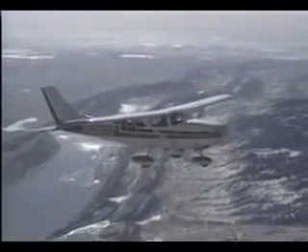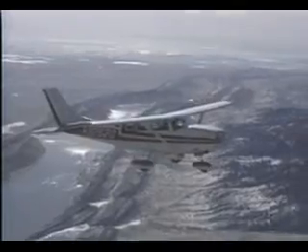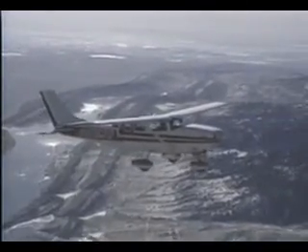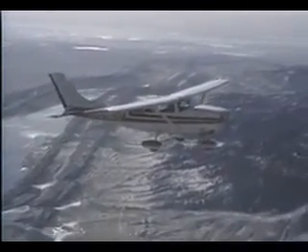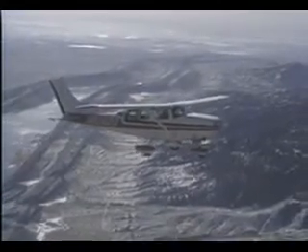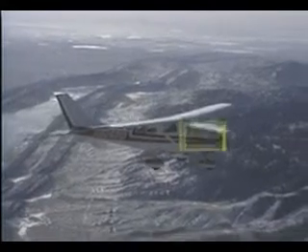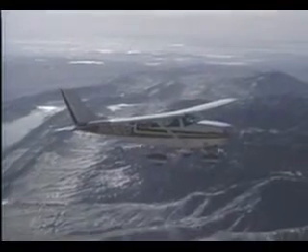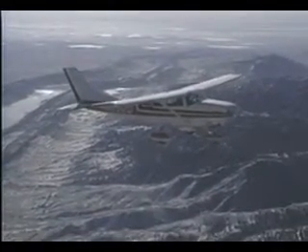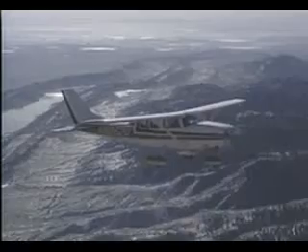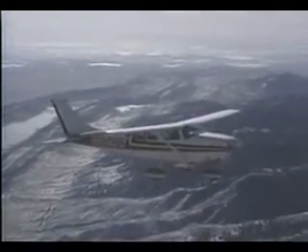Whether you fly airplanes with a carburetor or fuel injection, engine efficiency decreases as you gain altitude, and thus the density of the air entering the engine is reduced. To overcome this drawback, some engines incorporate a turbocharger that compresses the air that enters the combustion chamber. This increases the density of the air. Ultimately, the airplane is capable of operating at higher altitudes, since the engine can continue producing sea-level power as you climb.